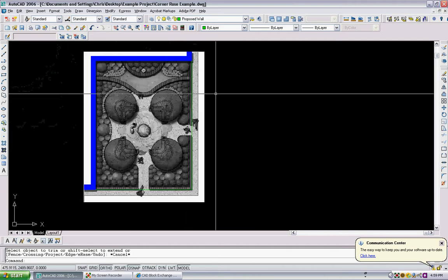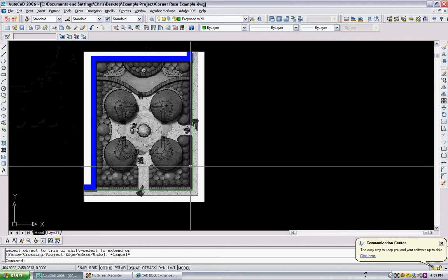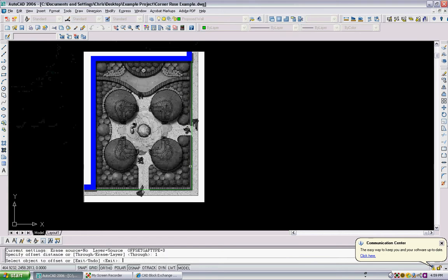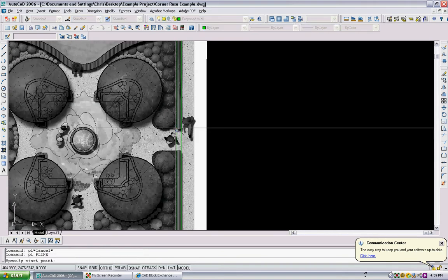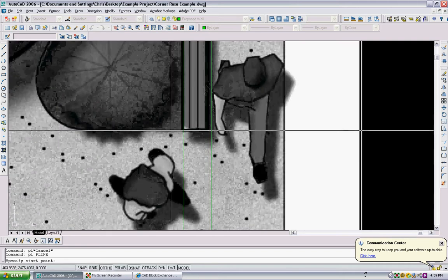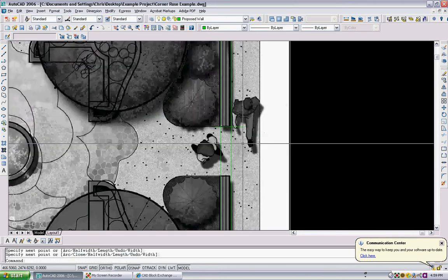Okay. Now I know that I made this thing a foot, so I'm going to offset and then type 1, enter. Offset, offset. Let me come back over here. Ortho should still be on. I'm just going to cut where this thing would break at.